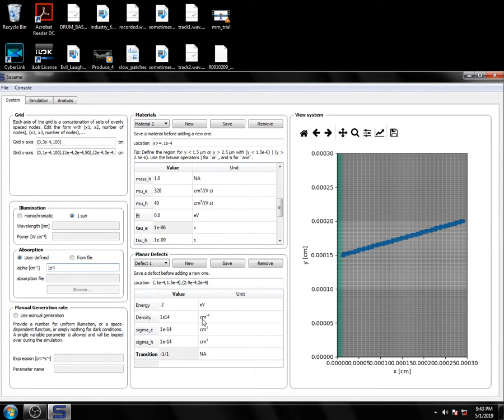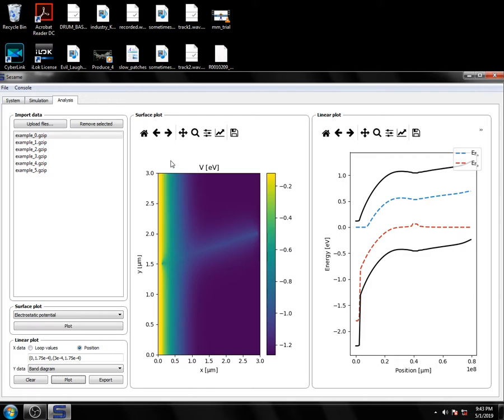Because of the requirement of electroneutrality of these potentially charged defects, and the fact that there are so many of these defects there, you have a strong modification of the electrostatics and the other properties of the solution. So it may not be so surprising that so many of these charged defects would distort the expected behavior of a typical one-dimensional NP junction.